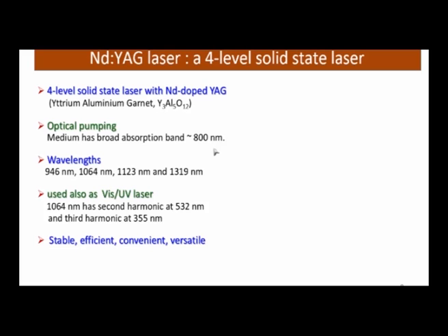In the case of optics, it is light we are talking about. In the other case, it is electric oscillations, of any frequency. So we have omega 1 and omega 2, we get omega 1 plus omega 2. Now put omega 1 equal to omega 2. Then what do you get? You get 2 omega. You give frequency omega and what you get is frequency 2 omega. This is called second harmonic generation.